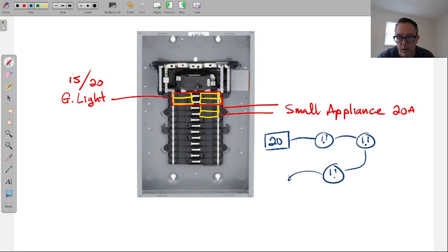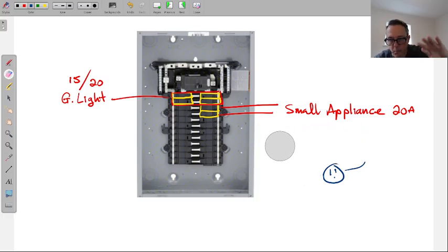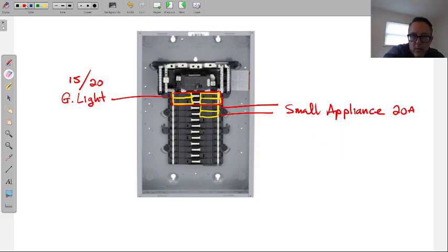So my point is, you don't want to put too many outlets on one small appliance breaker. That's why they make sure that it's 20, bigger than the 15. They want the maximum they can put. 20 is the max. So you also want to limit that. So again, engineering, we don't have to go that far deep into it. This is more of an engineering thing. We just have to know the breaker we're putting there and or replacing. If you have to remodel a kitchen, you got to know what breakers you're bringing into that kitchen area. But that's what it's for, small appliance.